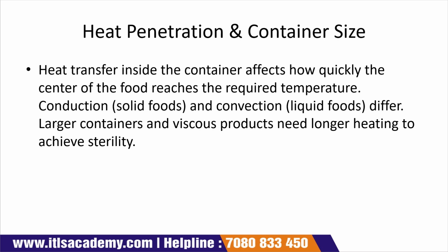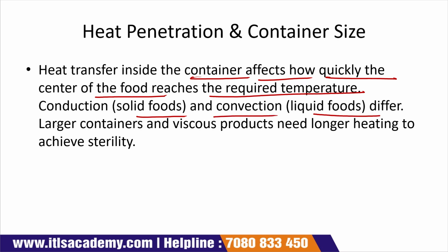Heat penetration and container size. Heat is transferred inside the container and affects how quickly the center of the food reaches the required temperature. Conduction for solid food and convection for liquid food. Larger containers and viscous products need longer heating to achieve sterility.